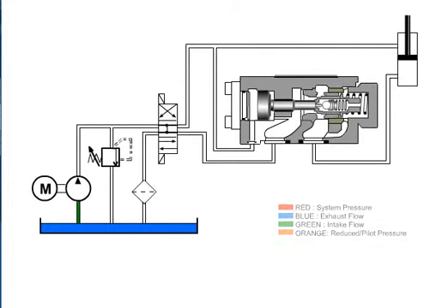Because of slight spool leakage on standard directional control valves, we must add a check valve to the circuit if we need to hydraulically lock a cylinder. This type of check valve is referred to as a pilot-operated check valve.